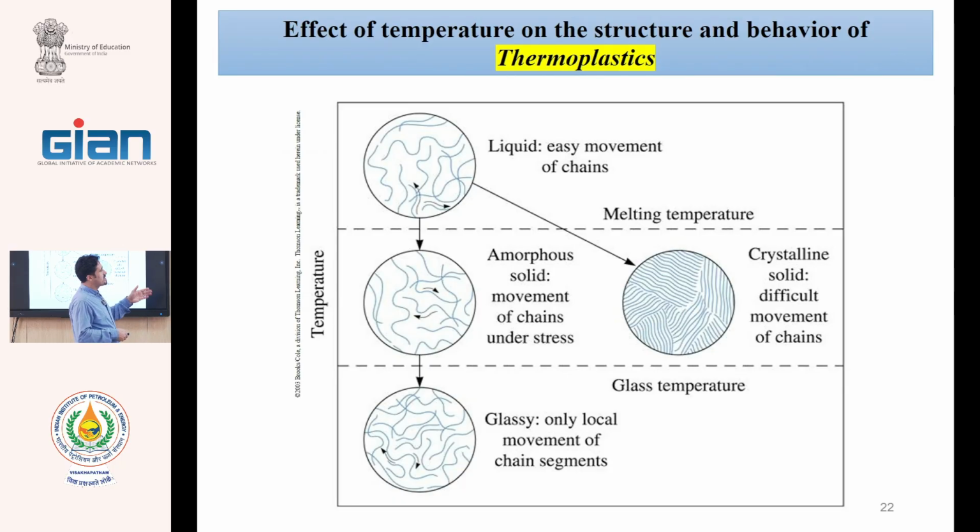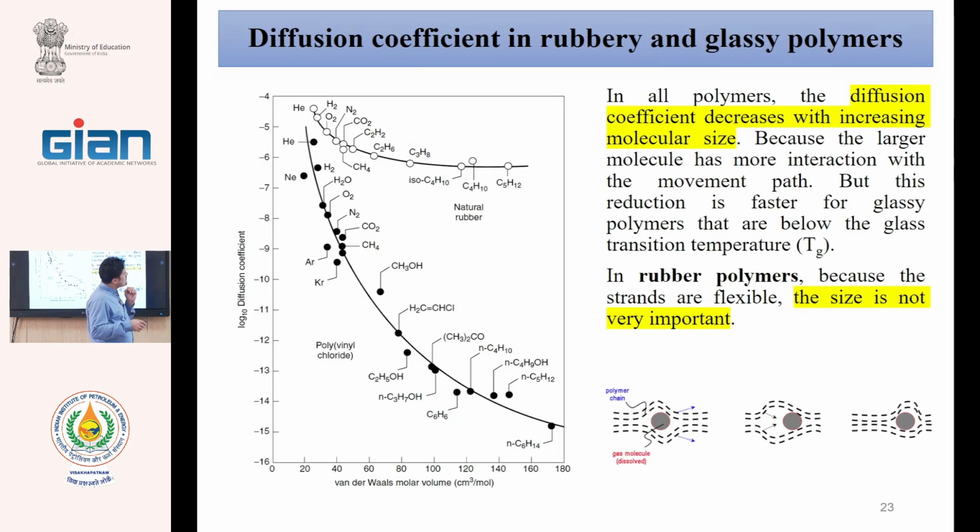Therefore, we have different behavior. The elastomer polymers at ambient temperature, at atmospheric temperature, are above the glass temperature. The elastomer Tg is minus 10 centigrade. That means 25 centigrade is located in this area, and they have flexible behavior. Based on this discussion, we have 2 parameters.